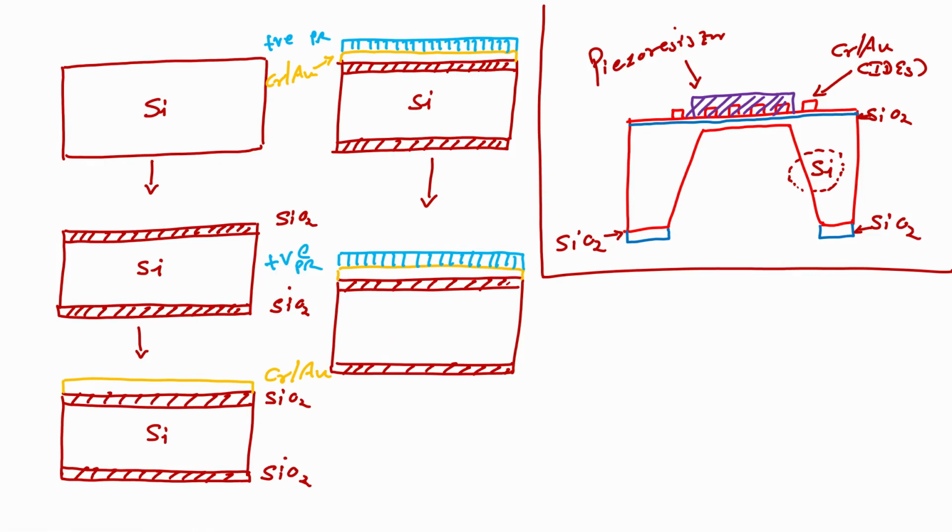On this we have to use a mask. Let us use a mask, and the mask is such that I have to only protect the interdigitated electrode, I want to pattern the interdigitated electrode. So, my mask would look like this. It is a bright field mask.